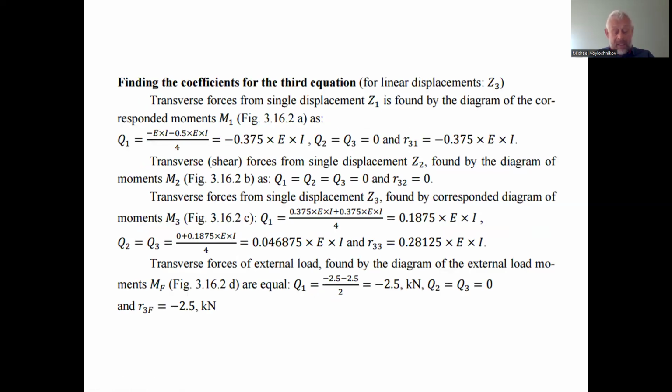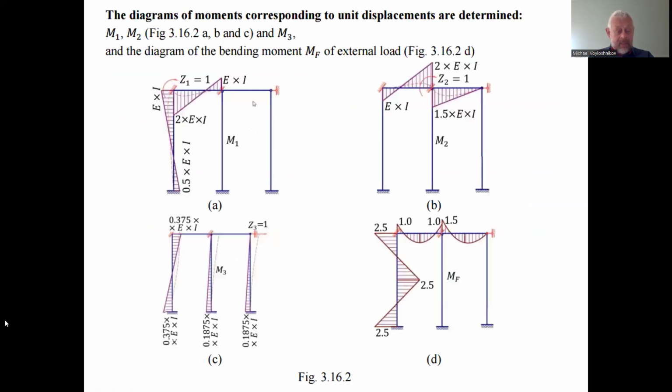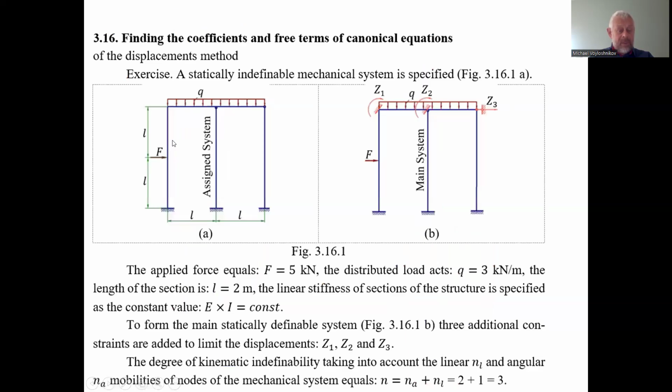to find what the force is, we use a derivative interdependence. So considering the bending moment diagram here, we have to find from this diagram what the longitudinal force is here. The force is equal to the derivative of the bending moment. If we have a linear bending moment diagram, and we know the magnitudes at the ends, and we have the span equal to 2L, where L, as I remember, equals 2 meters, the total height of the stand is 4 meters.